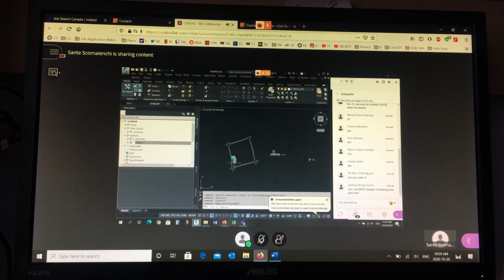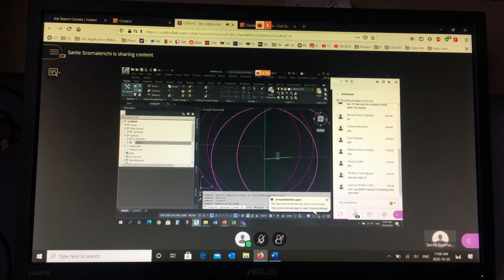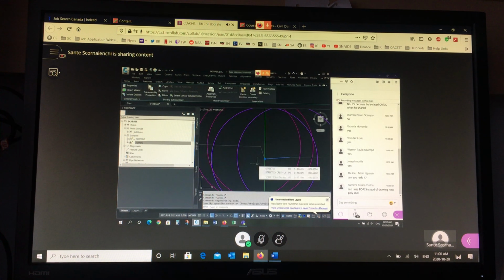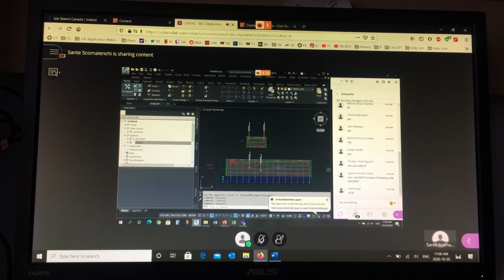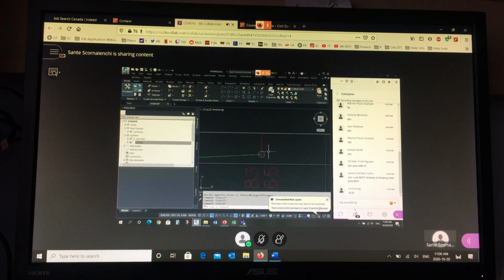So I have to go back to my profile, and 0.3 meters away, I want to put in my gutter. And remember the slope of the gutter? Anybody remember? The slope of this piece here? Carl, that's right, 8.33. So I'm going to come in here and draw a line. I'm just going to go 0.3 meters, so I have somewhere to target.